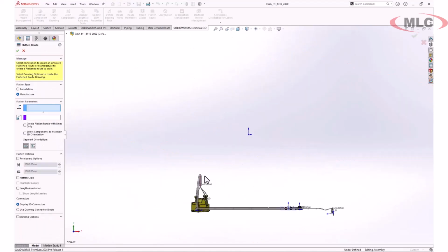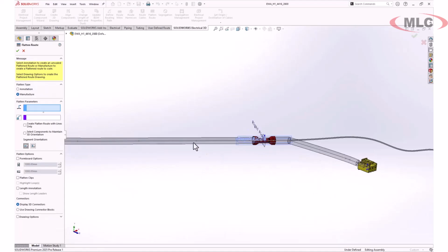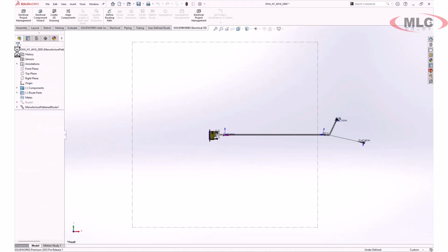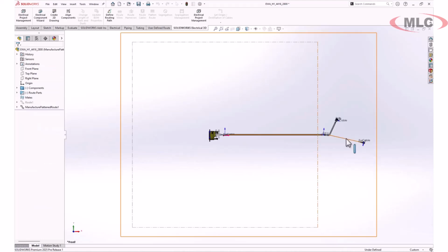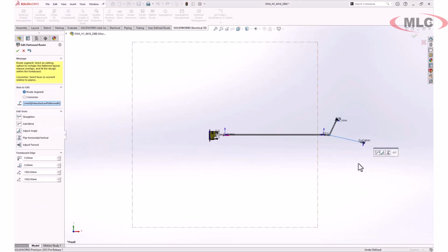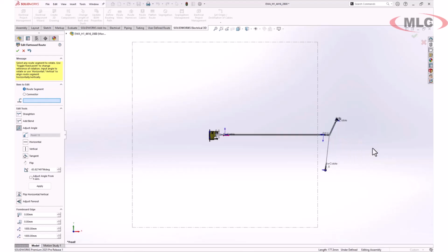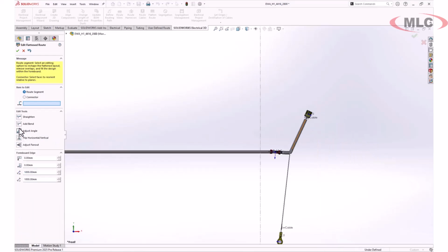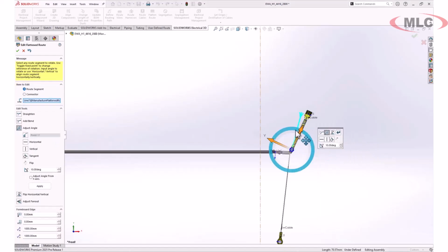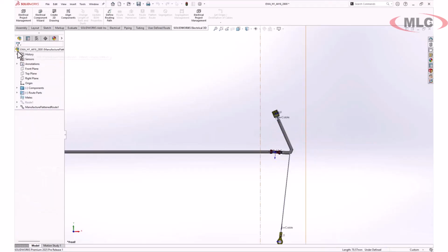The Flatten Route tool also offers improved support for complex and multi-circuit splices. For example, identifying the junction points and loop segments and moving them to the flattened plane. In previous releases, the editing of Flatten Route has been improved. You have this on-screen interface for making these fine adjustments to the flattened route. Even with this significant change to the harness, the drawing updates better than ever.